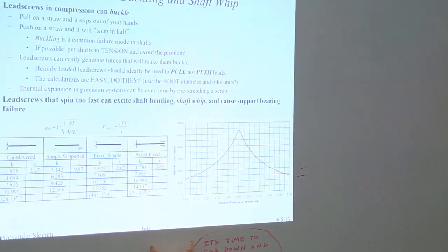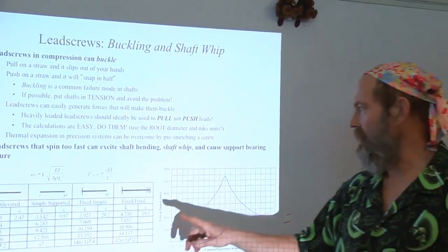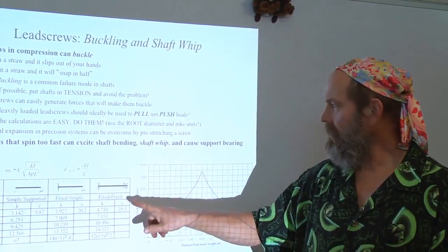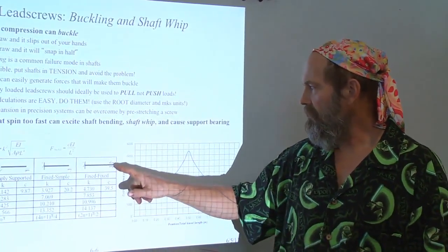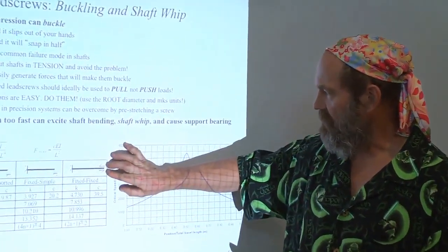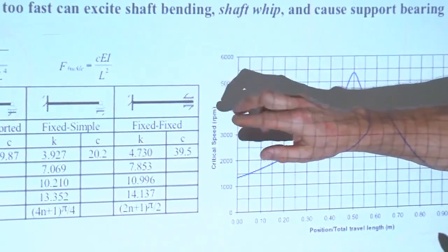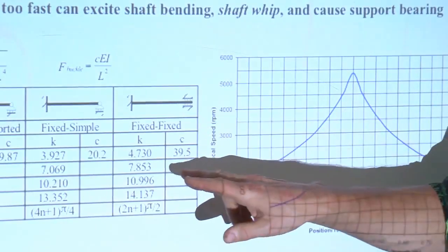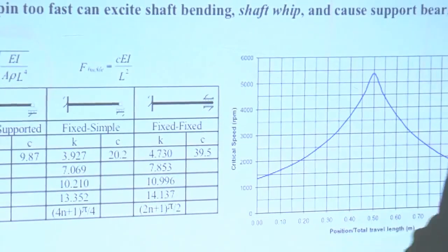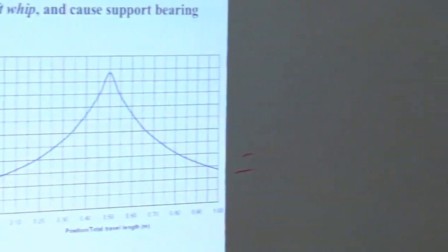Earlier, notice we had that your natural frequency can be much higher if the screw thinks that the end is a fixed support, right? It can be a factor of 10 higher with a fixed support than you would get if it was simply cantilevered support.